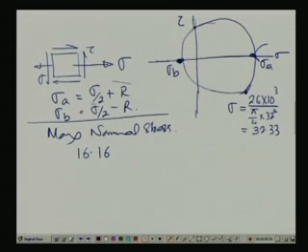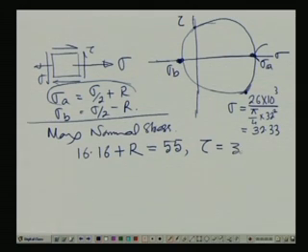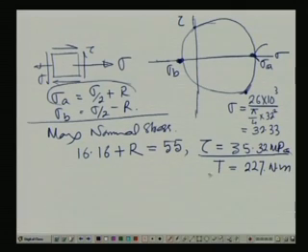The maximum stress value should be equated with the ultimate stress in the tension specimen. So, that means it comes out to be R, and that value in tension we got as 55. So, from here we get the shear stress tau comes out to be 35.32 MPa. I am not discussing more because it is a similar type of problem, only we have changed the theories and the materials. So, T equals 227 Newton meter.